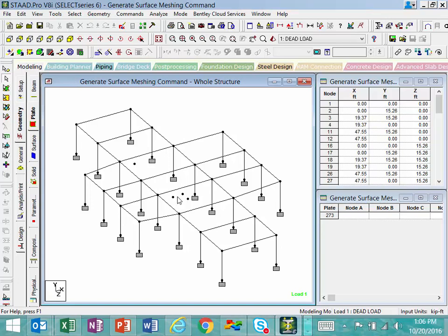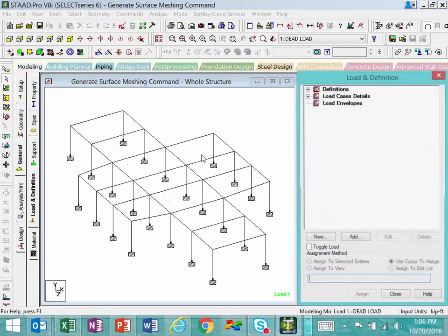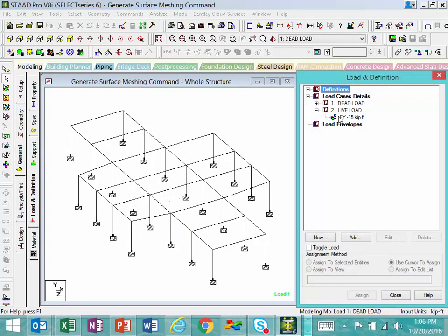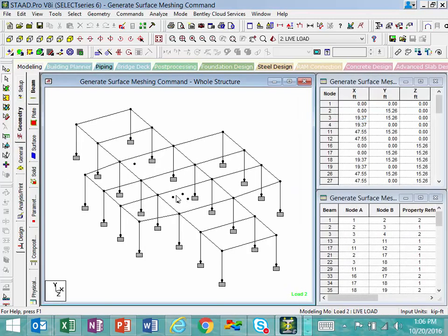Now within this particular model, I've also added a few extra nodes. So you're going to see some beams and columns. I have a node here which actually represents a point load on my slab. So you can see I've added a load right there. I also have these extra 4 nodes which will eventually represent a hole within my slab. You're going to see that with a parametric model, it'll be a lot easier to define a hole in the slab. And for me, I like to just create the nodes and then I can just add everything graphically, which is kind of nice.